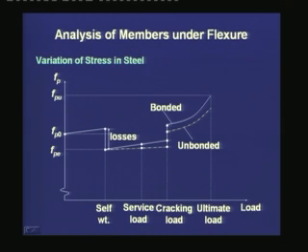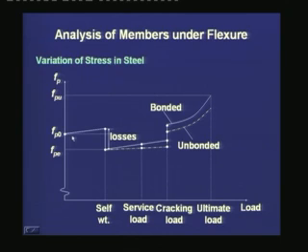In this sketch, what we see is that first the prestressed member has been stretched with a stress of a value Fp0 in the tendons. Now, as the self weight is acting, it can act either while the member is hogging up, or when the shuttering or the false work is removed. When the self weight acts, there is a slight increase in the Fp0, and then with time there is a drop in the prestressing force due to the long term effects of shrinkage, creep and relaxation, and it stabilizes to a value of Fpe.